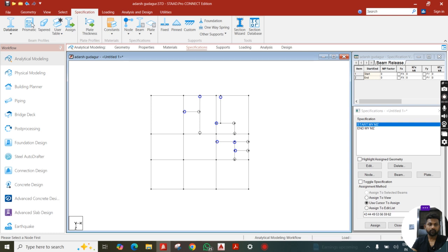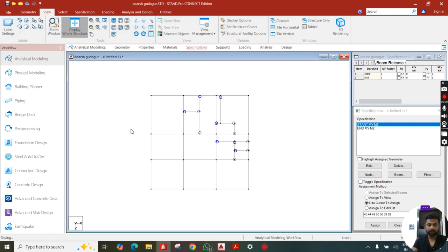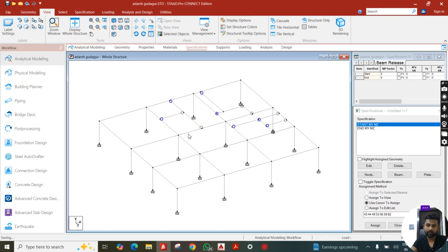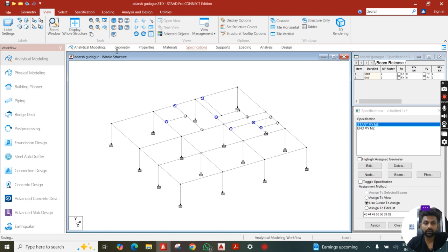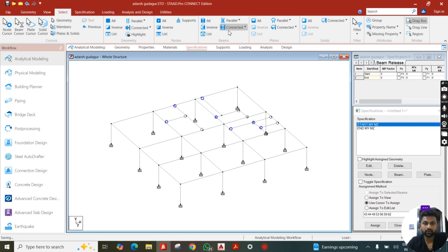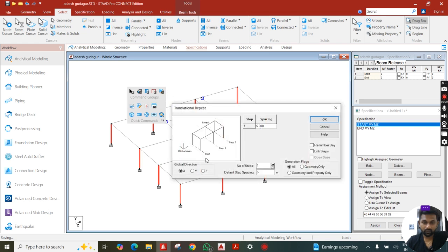Plinth beam is all ready. We'll save this first, we'll come back. So plinth beam is done, and now we'll select all the columns. The height of the slab is 11.5, clear distance is 11 feet. 11.5 feet is equal to 3.5 meters. We'll just raise it on top.